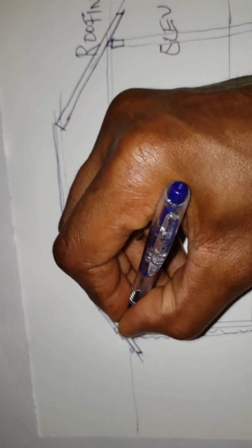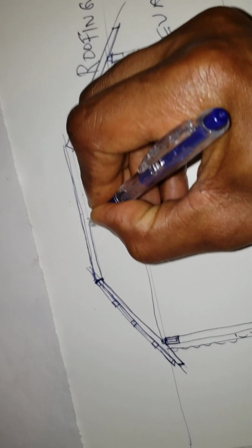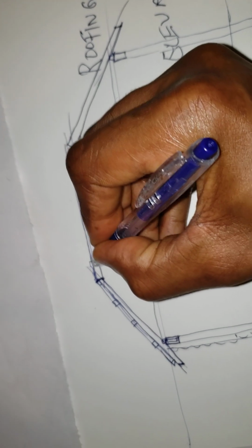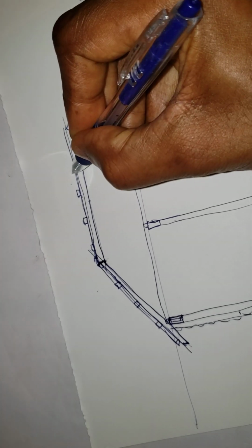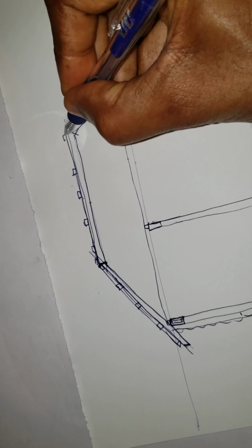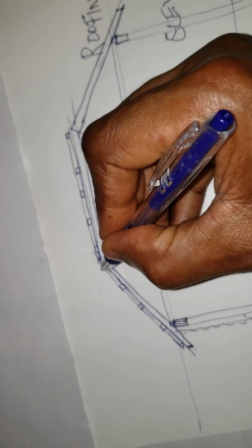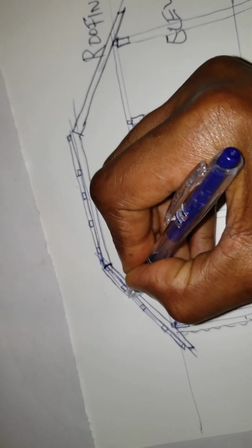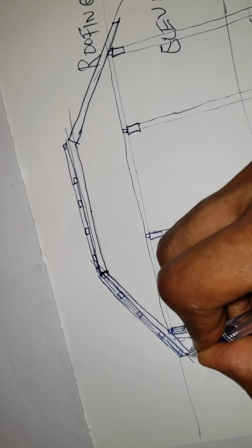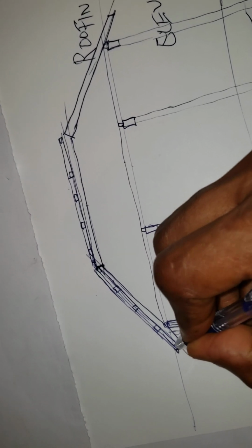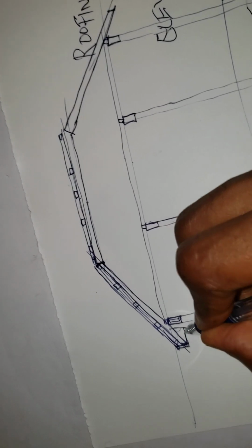Then we draw, and we'll do the same thing across here. Remember, these are 50 by 50. They should be square. And of course, that going across. And we would then place our sheeting material over here. One layer to represent that. Then our fascia board would be here. Our fascia board would be under here. And our soffit under here.